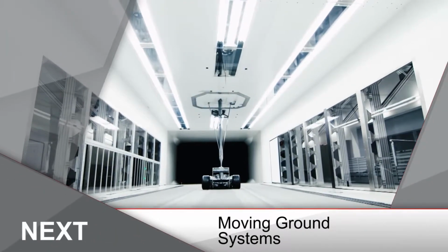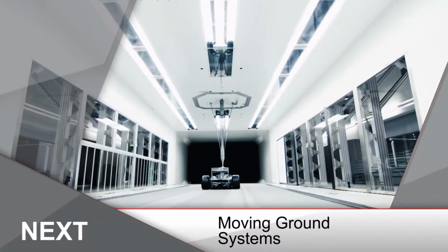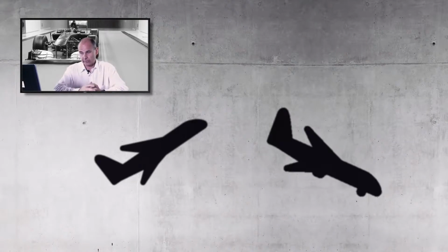So looking again at the test section, one of the areas that has been the subject of quite a lot of research over time has been moving ground technologies. Again, it's an area where motorsport has led the way, and the aircraft and aerospace industries use what we have developed for their takeoff and landing simulations. Now, when I first started working with moving grounds, it was literally like a conveyor belt, almost as crude as a supermarket conveyor belt, just with a lot of tension and then with a bigger motor to run it faster.